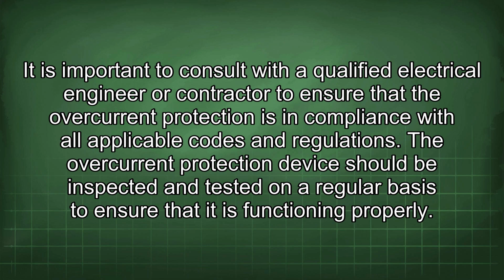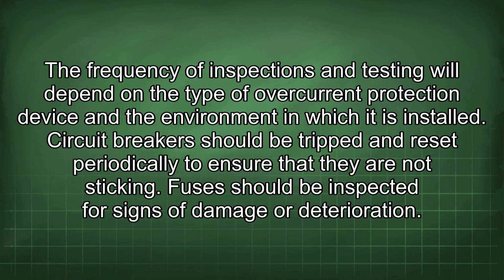The overcurrent protection device should be inspected and tested on a regular basis to ensure that it is functioning properly. The frequency of inspections and testing will depend on the type of overcurrent protection device and the environment in which it is installed. Circuit breakers should be tripped and reset periodically to ensure that they are not sticking. Fuses should be inspected for signs of damage or deterioration.